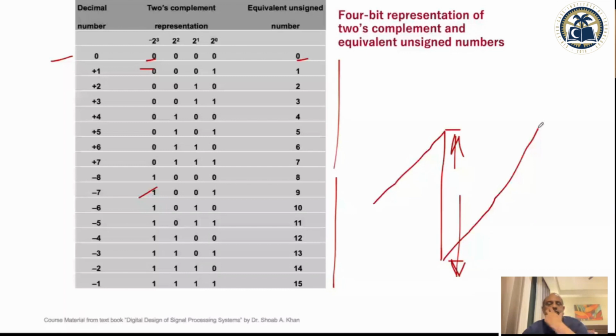So that's another issue with 2's complement arithmetic: an overflow has a big penalty on your computation, as +7 will not become +8, rather it will become -8, a negative number on the other side of the entire dynamic range of numbers. The error induced by just a little overflow is big.